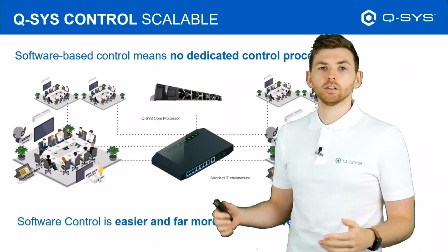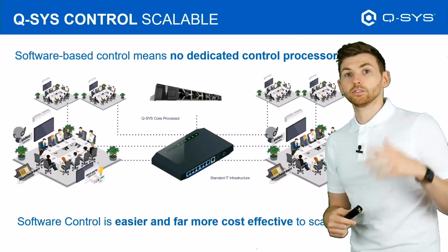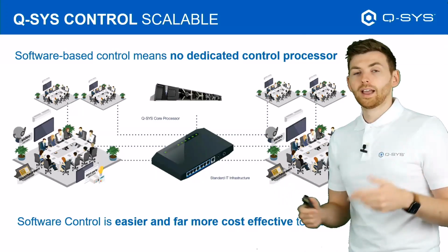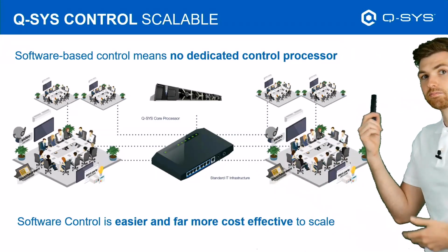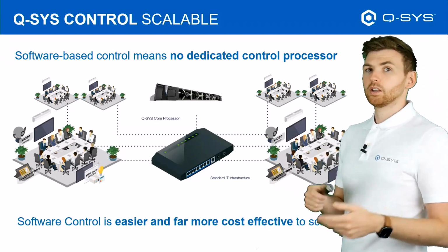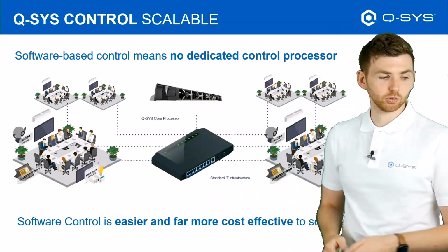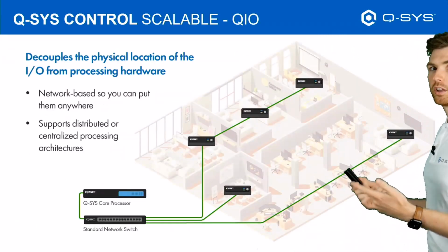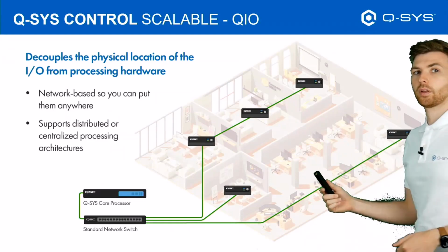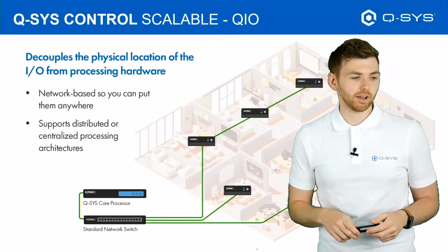Hundreds of control clients, not going to be an issue. And of course, that means you've got one set of scripting engine licenses, UCI deployment licenses, one core. And if you add on multiple rooms after the install, you don't have to upgrade the processing, probably. You can just update the program file on it to include the peripherals added in these new rooms. And when you look at the peripherals, you can see that instead of having the core in each room, here we've got peripherals in each room, but it all comes back to the same network, and that Q-SYS 10 is just hanging around in the background there.